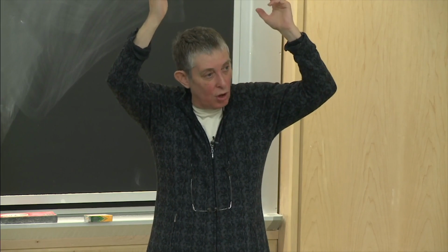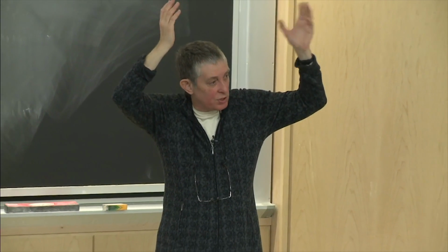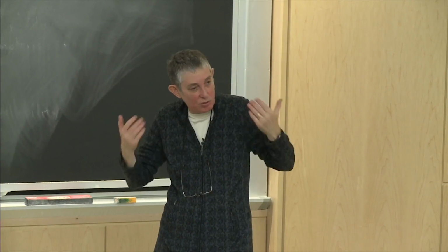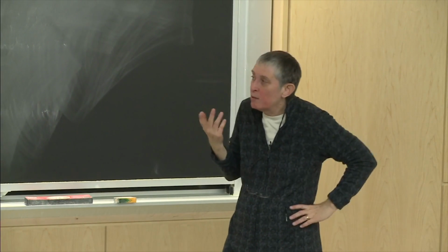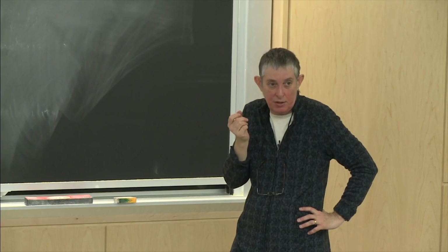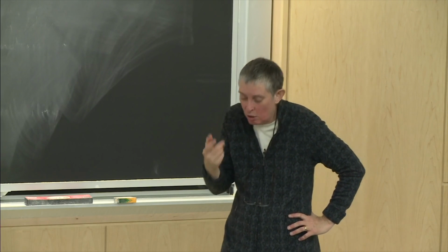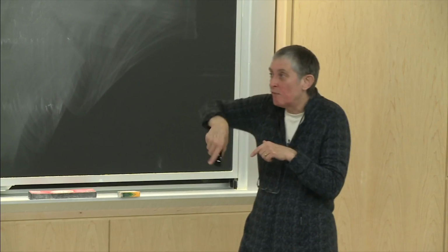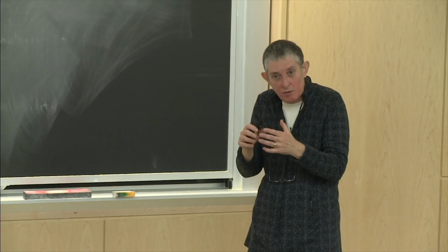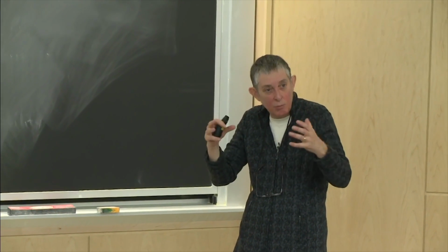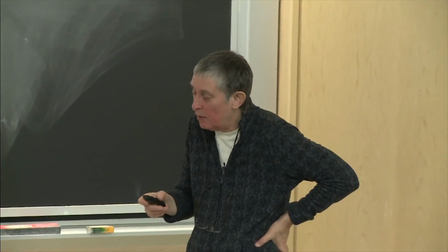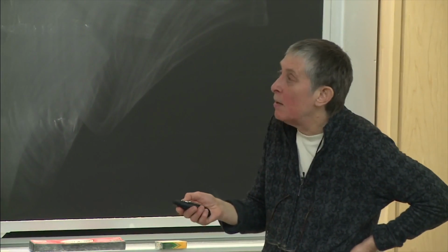As they get taller and taller, you can imagine that as wind forces and different kinds of forces act on it, the stresses get bigger and bigger. The way they resist those is that the cell walls get thicker, and they preferentially get thicker on the outside. Remember that moment of inertia is increased more by material on the outside of a beam, and that's kind of what the palm is doing.